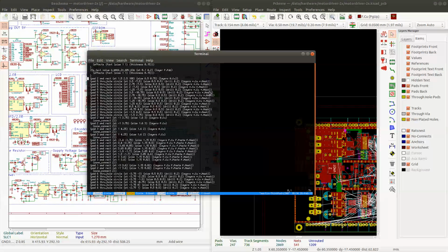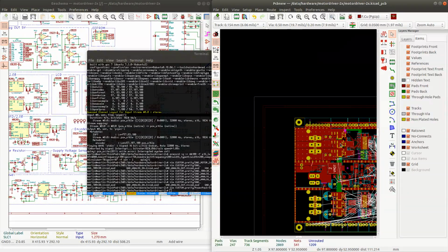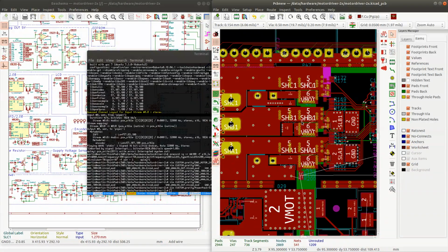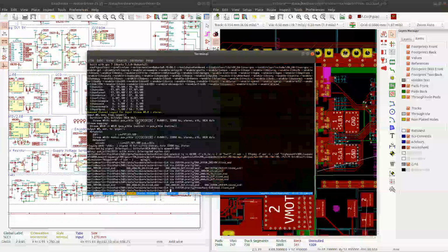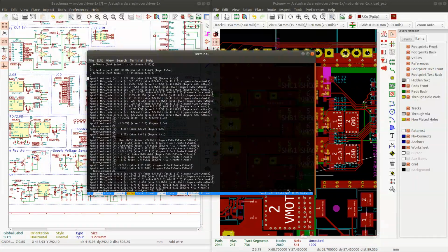But yeah, this one I'll just edit manually, because there are some pads that, or actually no. We need to match the through hole. So I shouldn't remove the mask from anything that's an SMD pad, but anything that is a through hole is pretty much without, yeah, all of the through holes are just emulated vias.